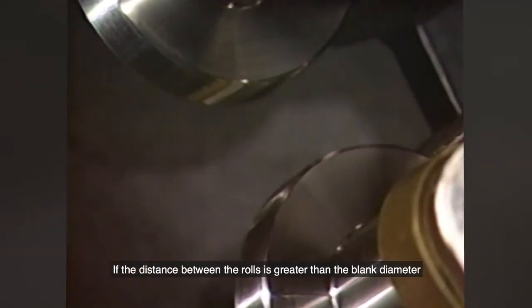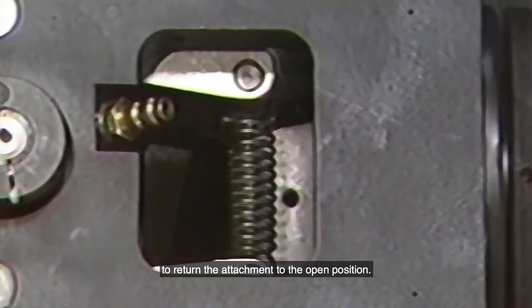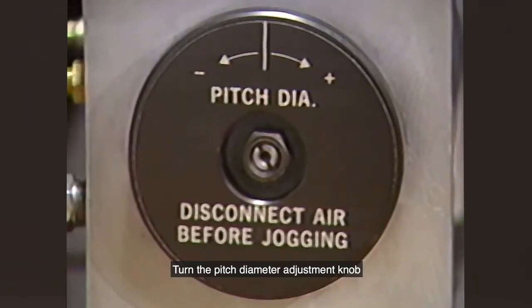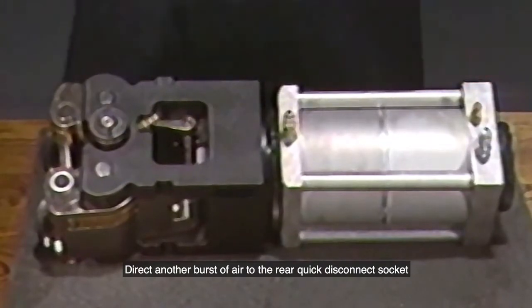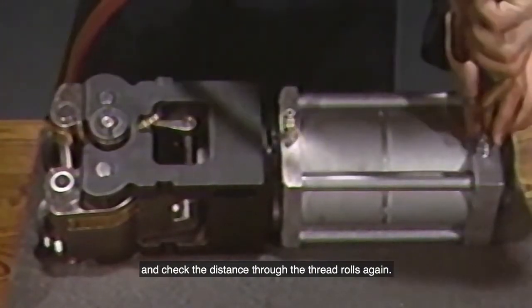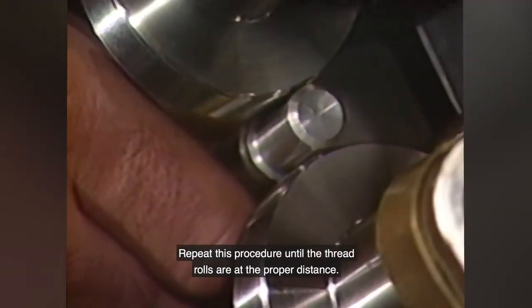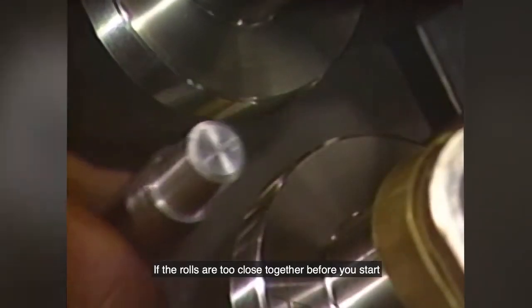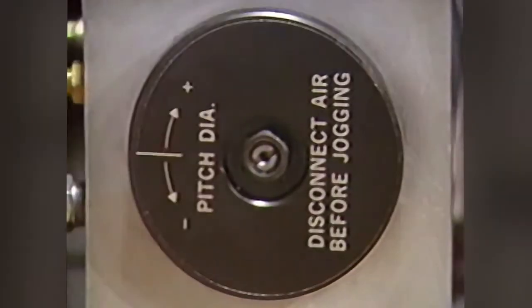If the distance between the rolls is greater than the blank diameter, direct another burst of air to the front quick disconnect socket to return the attachment to the open position. Turn the pitch diameter adjustment knob at the rear of the attachment in the minus direction. Direct another burst of air to the rear quick disconnect socket and check the distance to the thread rolls again. Repeat this procedure until the thread rolls are at the proper distance. If the rolls are too close together before you start, simply turn the pitch diameter knob in the plus direction.